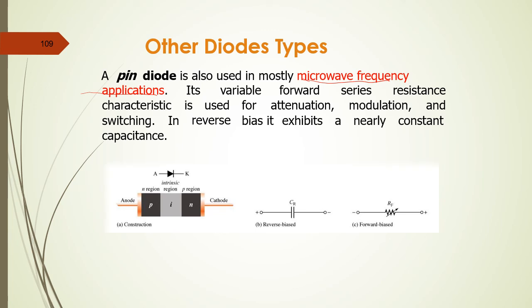The difference from the normal diode is that between the P and N junction, there is what we call an intrinsic region. Remember again, intrinsic and extrinsic. Intrinsic is the semiconductor material in a very pure state, so intrinsic has poor conductivity. If you recall, in the diode, where we have P and N junctions, in the boundary we have the depletion region. This one doesn't have the depletion region. Instead, we have an intrinsic region. Okay, that's for your knowledge.